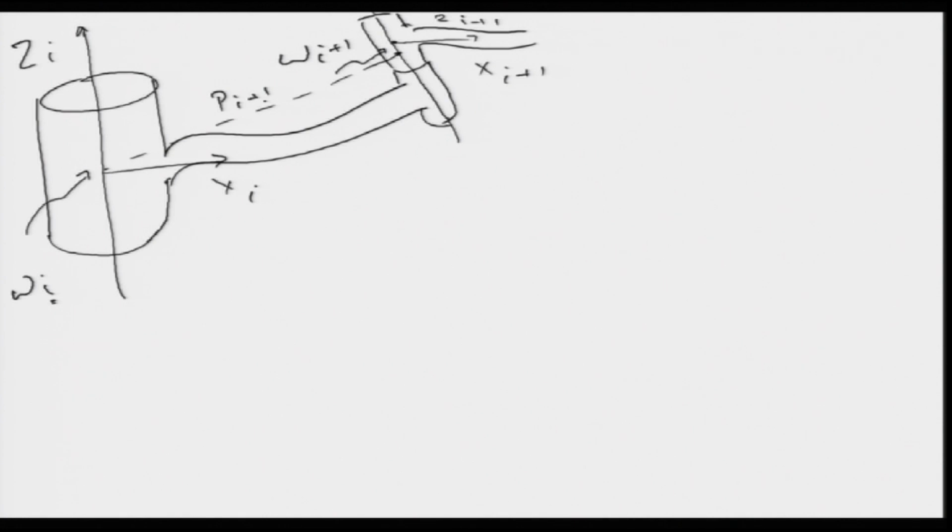Okay. So, now we are saying is that because there is an angular velocity here, this velocity will tend to propagate from the ith link to the i plus 1 link. So, velocities will propagate from the i to i plus 1th link. And because there is a distance between the origins, between the axis and the origins of i and i plus 1, and the distance is p i plus 1, this will also experience a linear velocity. That is something we just saw, that this is a point which is moving about this axis, and hence it will also have a linear velocity.